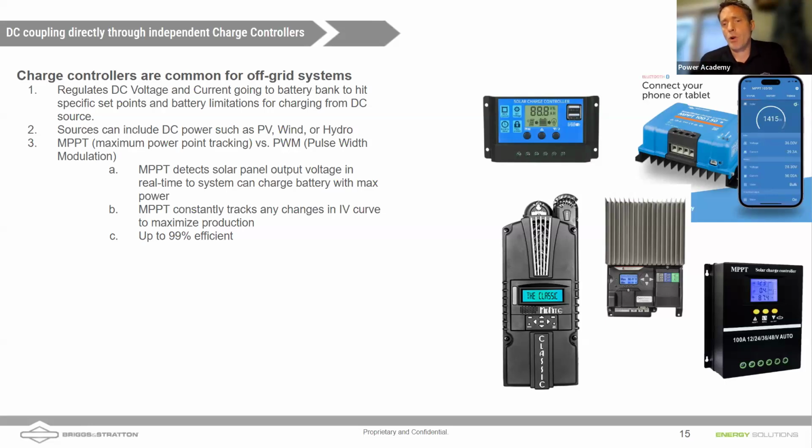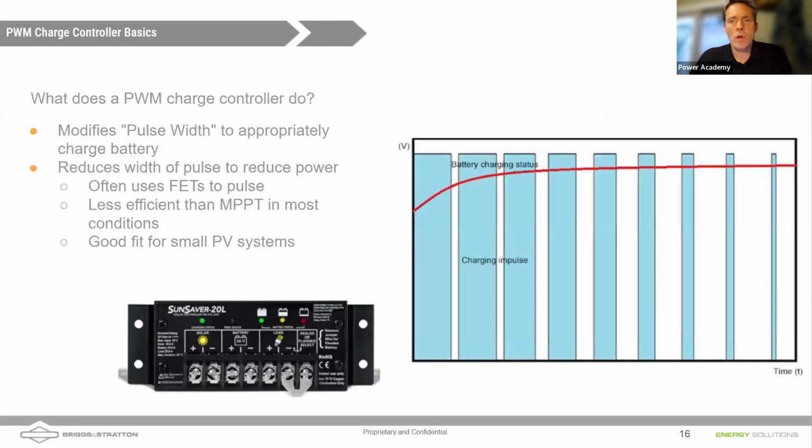They're typically current limited, right? So you can have a certain amount of current that comes out, and the power out of one of those devices, you get more power when you go to higher voltages. A PWM charge controller produces a voltage by modulating the amount of time, essentially by getting an average of the voltage.